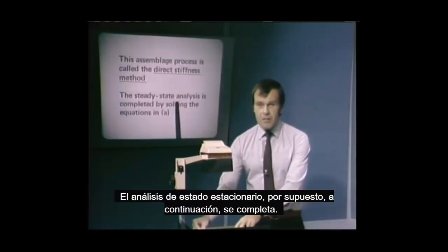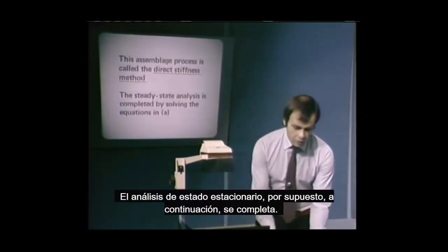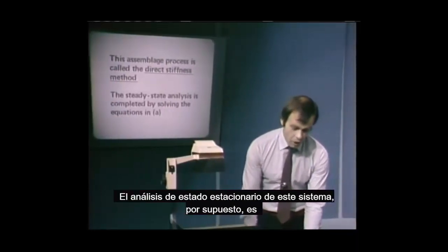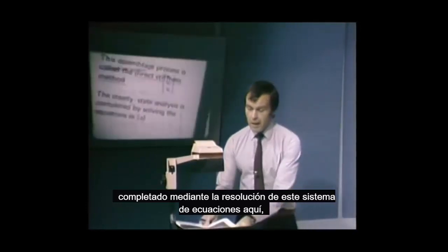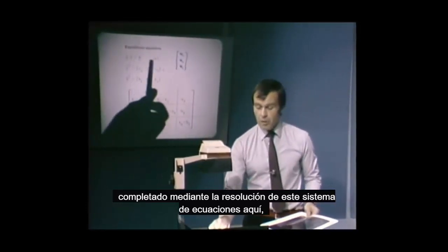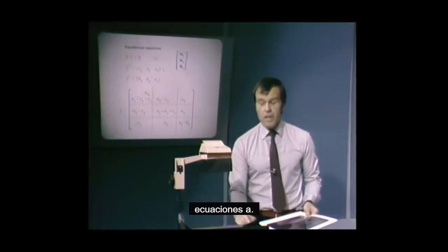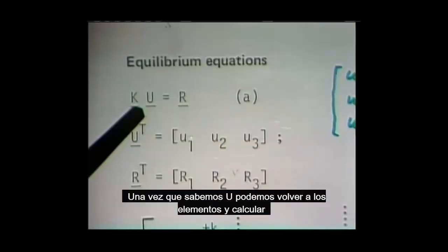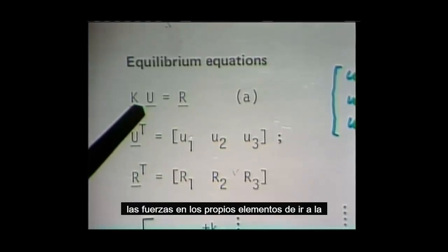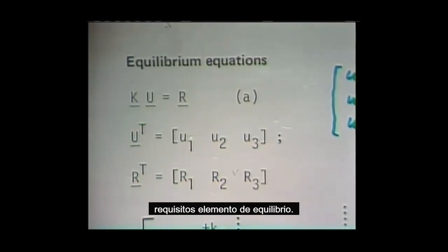The steady state analysis of this system is completed by solving this system of equations here, equations A. Once we know U, we can go back to the elements and calculate the forces in the elements themselves by going to the element equilibrium requirements.